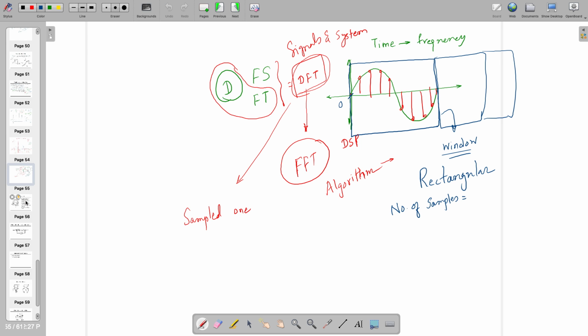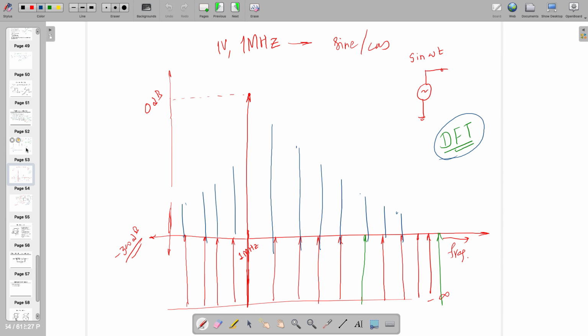These numbers are very specific, and to achieve minus 300 dB needs real mathematics for the number of clock cycles and number of samples. Sometimes you have to skip some of the cycles, because initially you will get something like this. Maybe you can skip one or two windows and then check the output, right? All these things depend on your expertise or understanding of this particular spectrum.